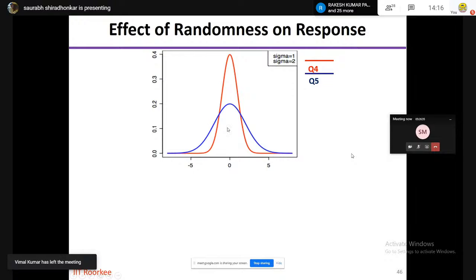So when I'm saying my standard deviation is large, it means that my structural response is highly uncertain. And when structural behavior is highly uncertain, we need to ensure that we are designing it for higher forces or lower capacity bounds to ensure that it has least chance of collapse or least chance of getting damage during an earthquake.